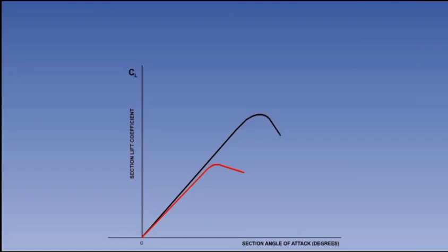It is thus better to use an airfoil that is efficient at high cruise speed with an ability to increase the camber temporarily when it is necessary to fly slowly, such as on approach. This can be achieved by the use of hinged sections of the wing trailing edge and leading edge, collectively known as the flaps.